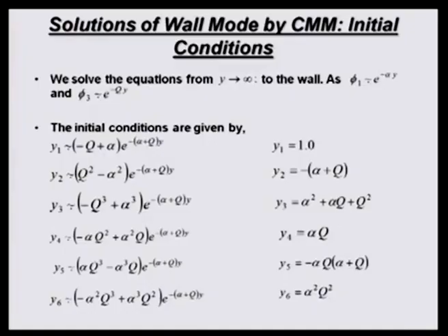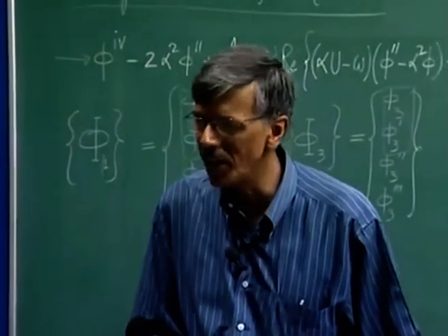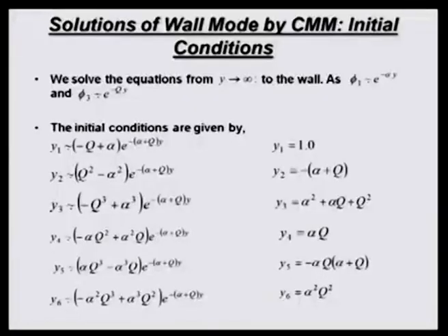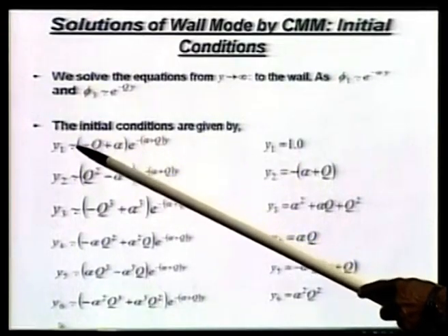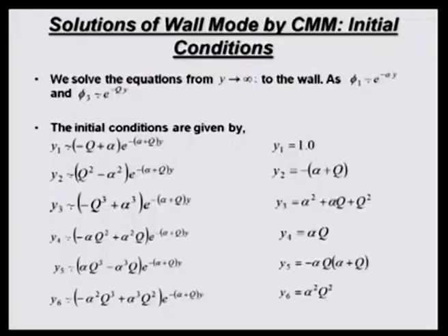And you know, when you are solving a stability problem, the quality of the solution you cannot exactly quantify. So, that is why I did not put an equal to sign here. I said y 1 goes like this, y 2 goes like this. The exact multiplicative constant is not known, because we are solving an eigenvalue problem, we are not solving a receptivity problem. In the receptivity problem, we would have prescribed the quantum of excitation at the wall, and then we could have walked along that line.